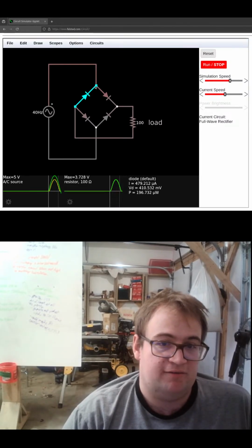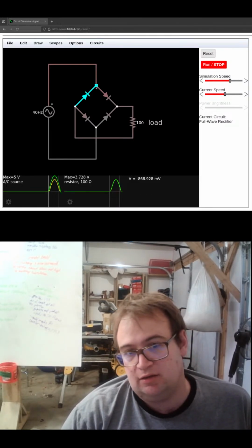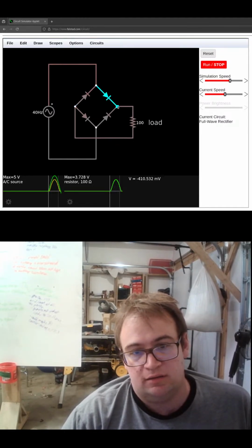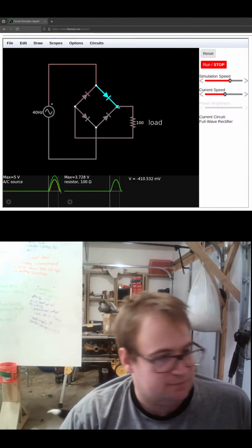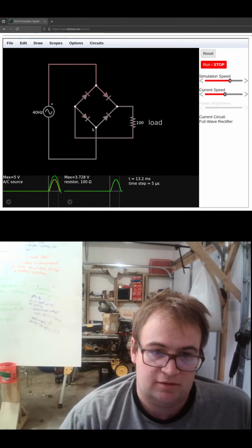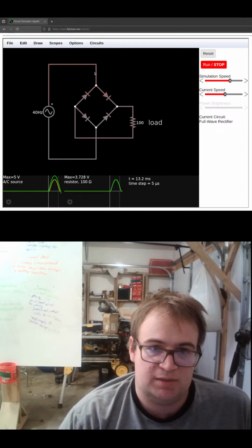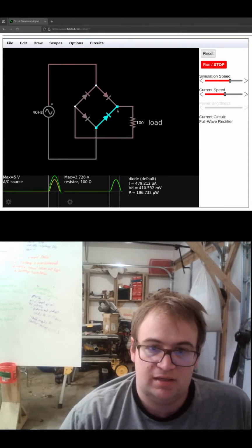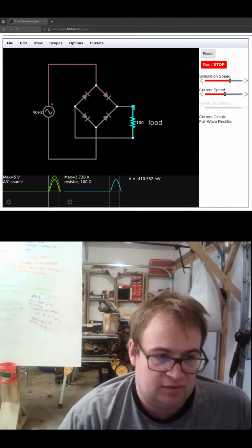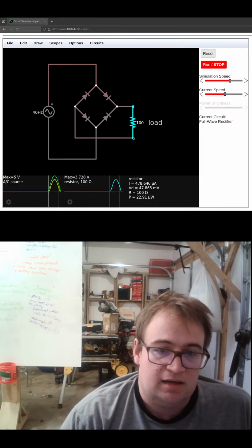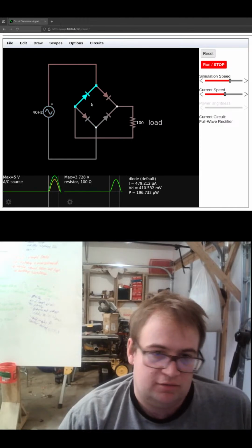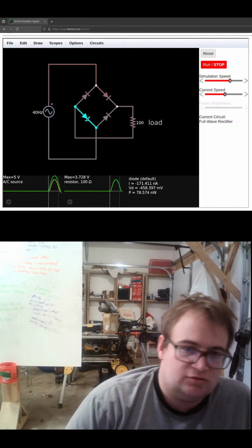We have plus 5 volts here. Well, we're going to go through here. We're going to be blocked here. But we'll go through here, and then out, and through. And then this load will go through this way. So what we're going to experience is the current's going to flow this way, there, into the load. So we're going to have about that 4.4 volts again here. And then out, down, and into the ground, or back into where the AC source is.